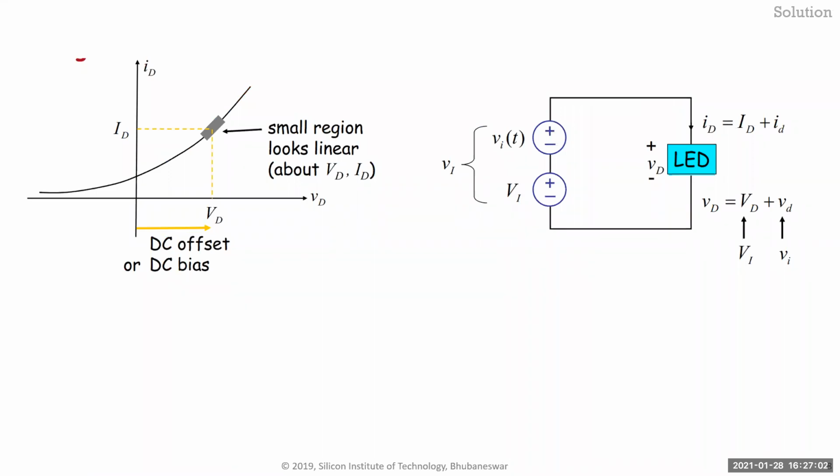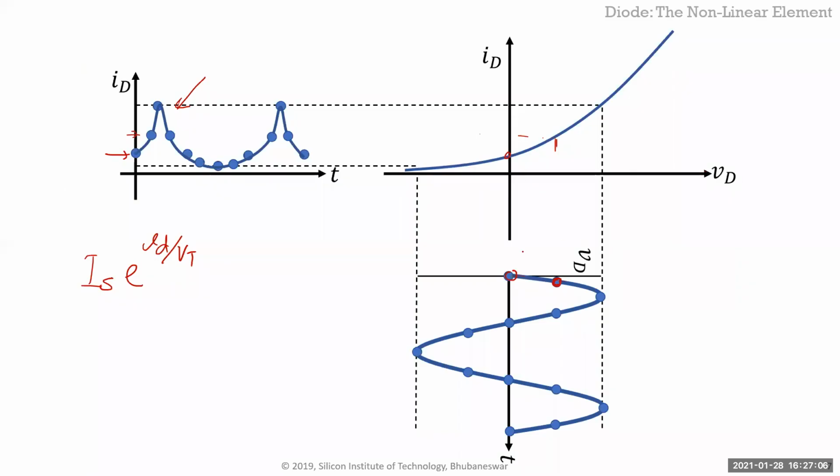So what you do is, if you look at this curve, you say, okay, if I use this entire thing, it's very nonlinear. But what I'm going to do is use a very small portion of it. Okay. And that's very linear. And then once I receive the signal, I'll amplify it, right? Because the whole nonlinearity is happening from voltage to current conversion in the diode. So instead of giving a large variation in the voltage, I'll keep the variation small, right?